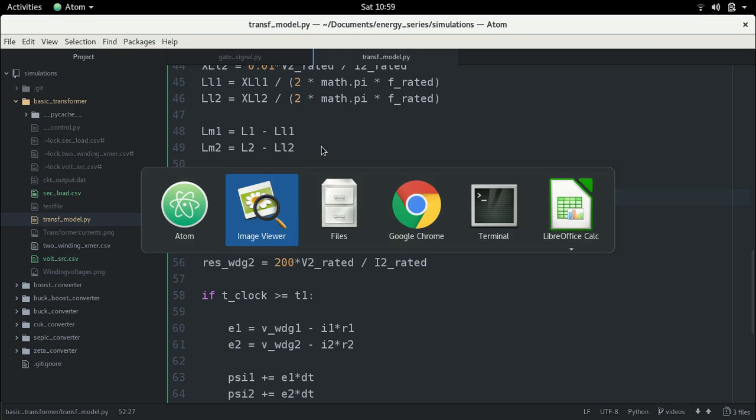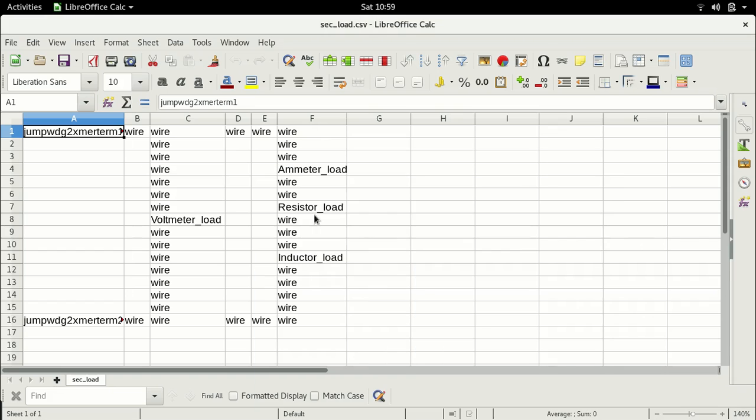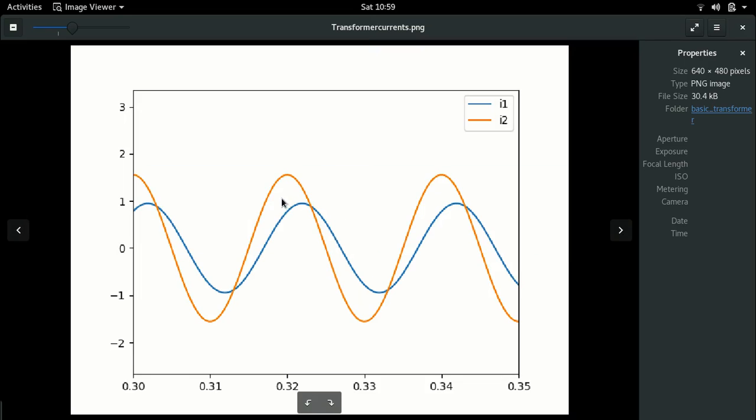So for example, in this circuit, if I were to make this load very large, extremely large, such that the current were negligible, in that case, there would still be a current flowing in the primary. This current flowing in the primary is the magnetizing current that the transformer draws from the energy source to sustain the magnetic field, right? This is always going to be drawn.